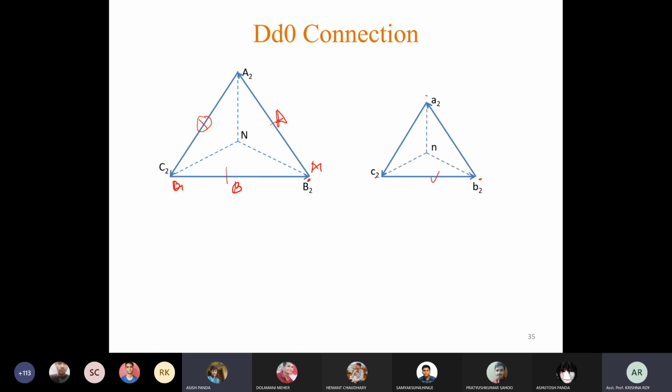Okay, so let us identify all the phases. So here this one is A phase, so this one will be A1 terminal, that means A1 and B2 are shorted, and same way we have to mark this phase as the low voltage side A phase because these two phases are wound on the same limb, so they must have 0 degree phase angle. So phase voltage, this phase and this phase will be parallel.